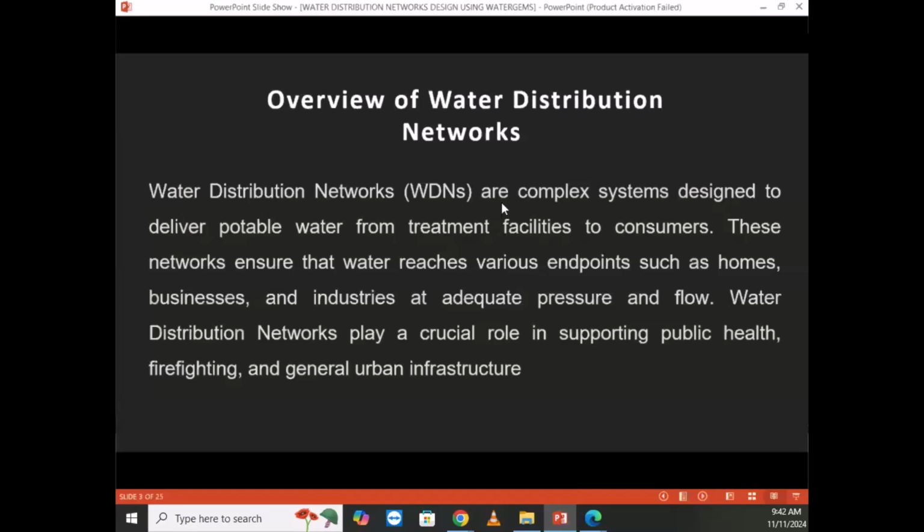This is also accurate because when you have the treatment plant at the source, it helps you most of the time. There are cases where the source is down at a lower elevation. It's encouraged to put your treatment plant near the source because by supplying dirty water, you will need a big capacity pump, so this will cost you much.